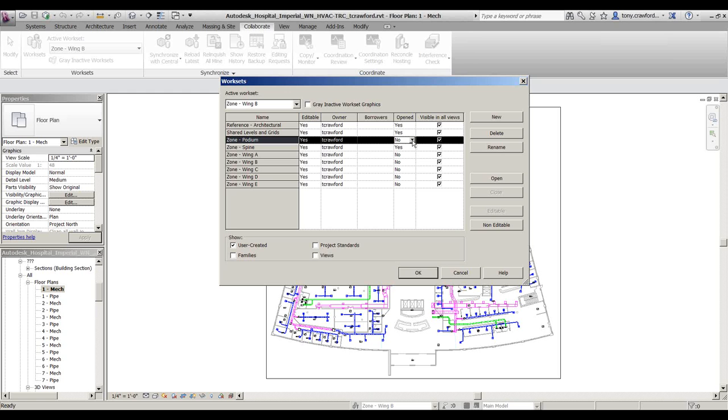But for best performance, close them out in all views, and then Revit basically ceases to think about those things. Not altogether, it still has to move them when it's moving a wall or a grid or something like that, but it doesn't load it into your cache to think about it from then on. It's doing the minimal amount of work. So that giant calculator called Revit in front of you is not processing every little calculation on the room volumes or something like that when you go to move a wall around.